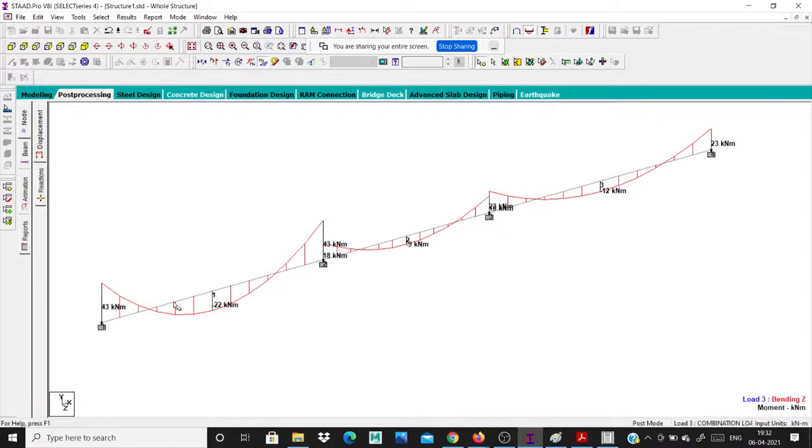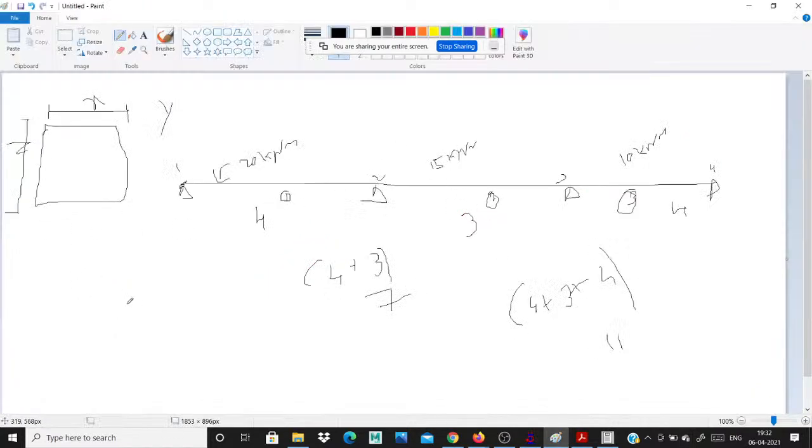The beam has the cross section in three stages, right? Simply supported means you give one cross section, but see this. This is our longitudinal simply supported beam, right? Yesterday we discussed, right? I cut this cross section. See this, automatically this is a hanger bar straight for simply supported, and this is a tension moment bars, right? Tension zone moment bars.